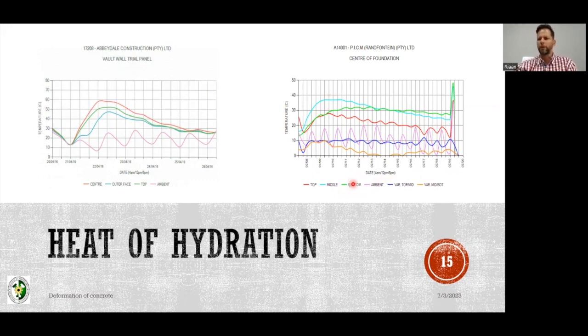So while we are there, put another probe, and you can see that the temperature on the bottom of the concrete, literally on your compacted subgrade, also followed the gain in temperature. And then at some point, the temperature of the concrete above started to cool down, and the base also started to cool down. But at some point, the base was warmer than the actual concrete on top of it.